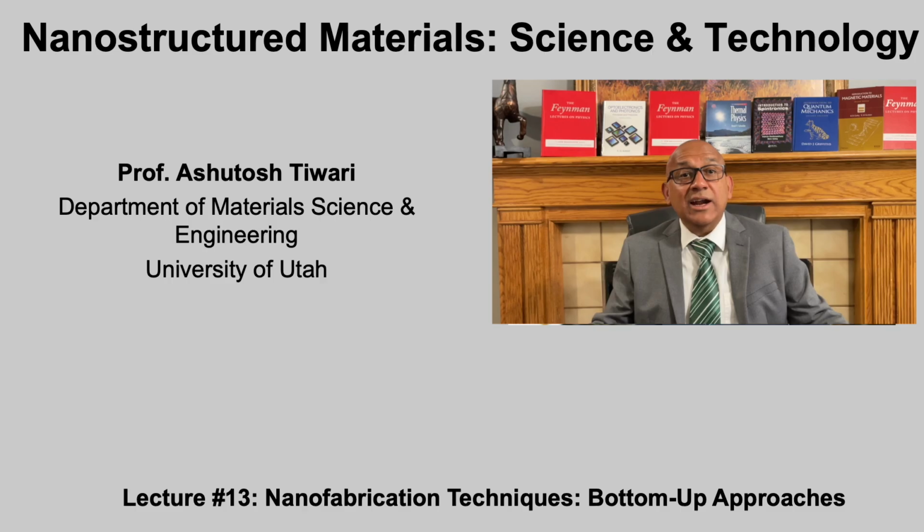This approach lies at the heart of modern nanoscience, from the self-assembly of DNA and block copolymers to chemical and vapor phase synthesis of nanoparticles, nanowires, and thin films. By the end of this lecture, you will understand how bottom-up methods achieve atomic scale control, enable uniform growth of nanostructures, and often provide a simpler, energy-efficient route to producing materials with remarkable precision. Let us begin by contrasting bottom-up and top-down approaches of fabrication to see how each contributes to the creation of nanostructural materials.